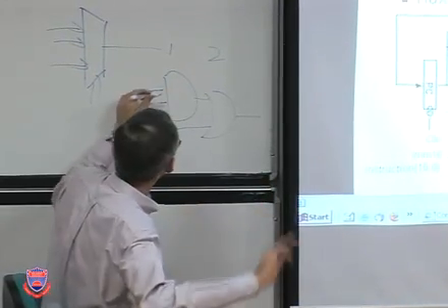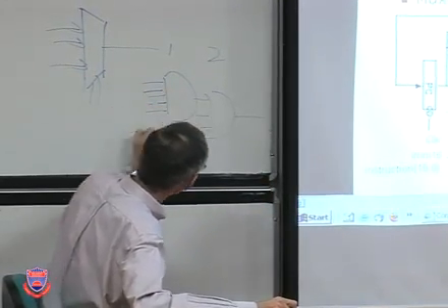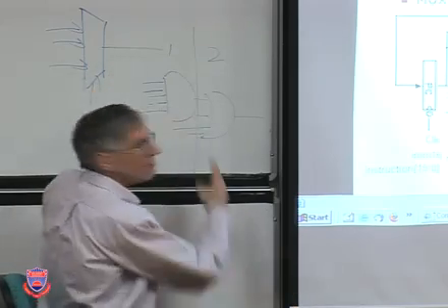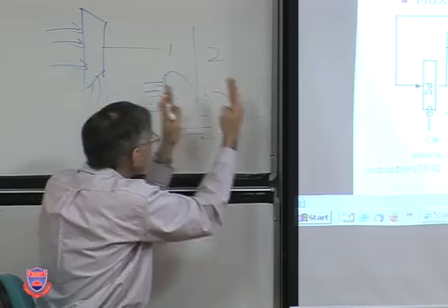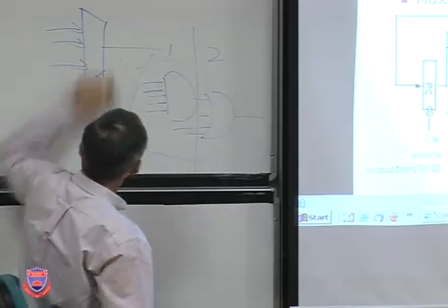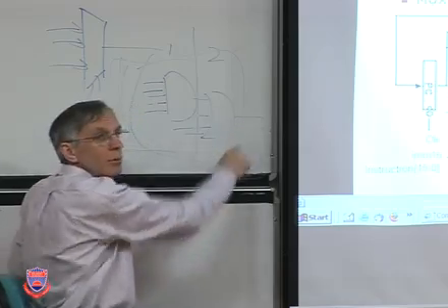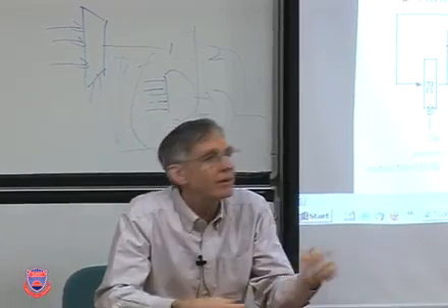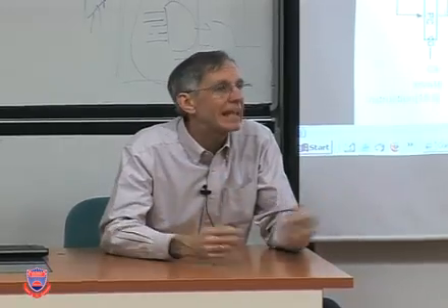Okan, I'm just asking this: can I do this? Is it still a 2-level if I do that? Yeah, it's not about the number of inputs. It's about the number of levels. That's the first gate level. That's called the second gate level. If these are the overall inputs and this is the overall output, it's a 2-level implementation. It's a 2-level circuit. If I have 3, it's 3-level. If I have 4, it's 4-level. If I don't know how many, it's n-level.